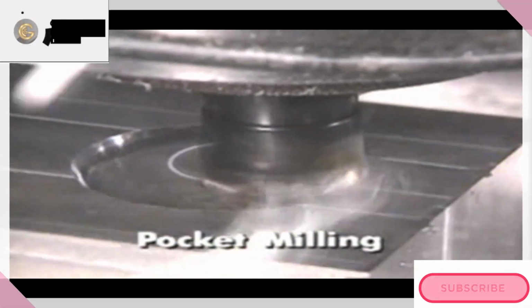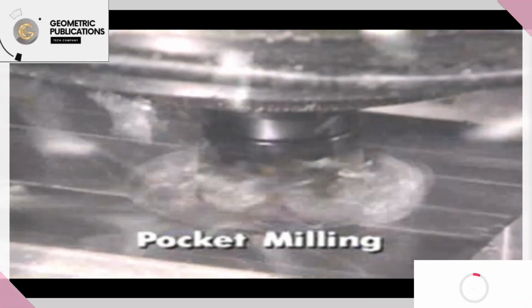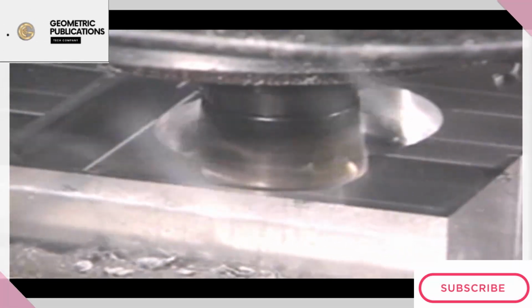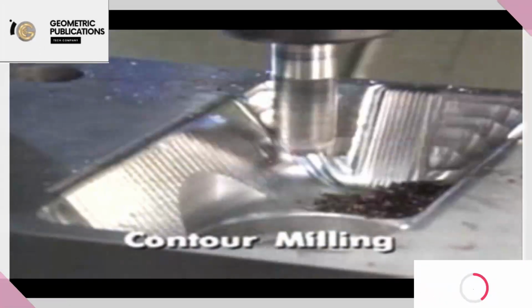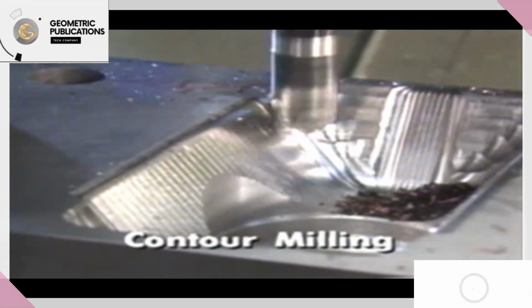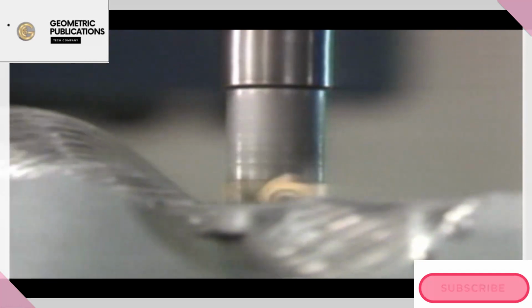Pocket milling means the tool, an end mill or small diameter face mill, drills down to a certain depth and then mills out from there to create a shape, often with a flat bottom, called a pocket. Contour milling sculpts intricate curved forms in 3 dimensions and is essential for die and mold making. Contour milling is most commonly performed using an end mill, such as a ball nose end mill.